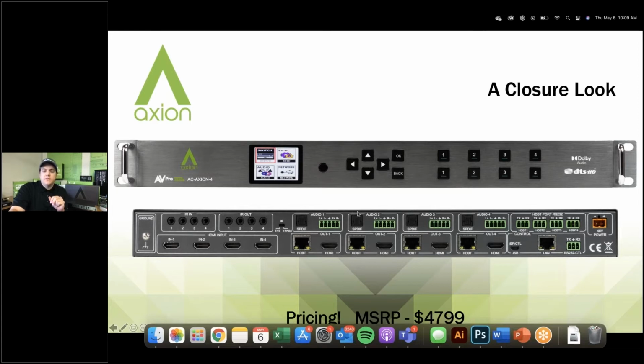These are completely configurable however you want. But what happens is if it goes in Dolby Atmos or DTS:X audio here, you will pass that through the HDBaseT and HDMI port so that it can go into an AVR and go into more speakers. But with the audio port, that's going to downmix that signal to a 2-channel signal.